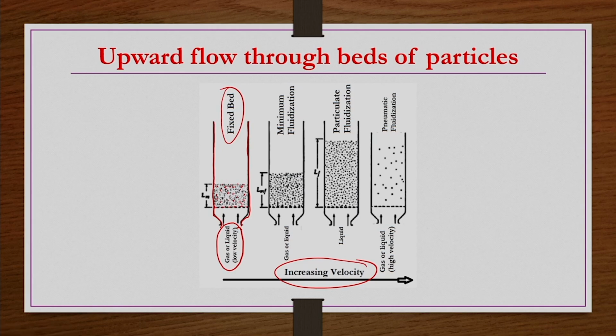Remember, whatever we are going to discuss in this lecture is primarily confined to liquid-solid fluidization only. Why? Because to some extent, whether the fluidizing medium is liquid or gas, the behavior is the same, but after a certain value of the fluidizing medium velocity, the fluidization behavior changes.